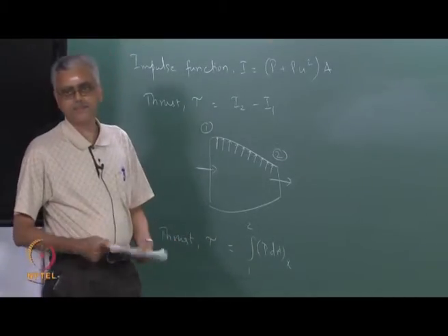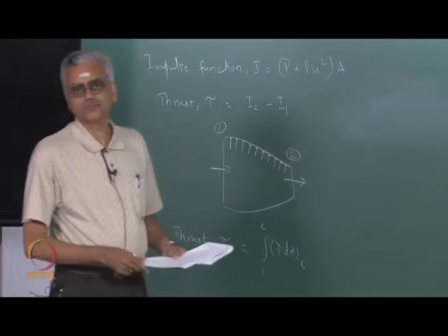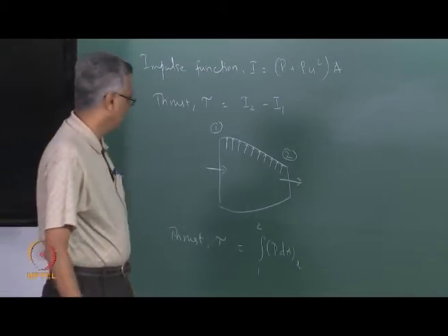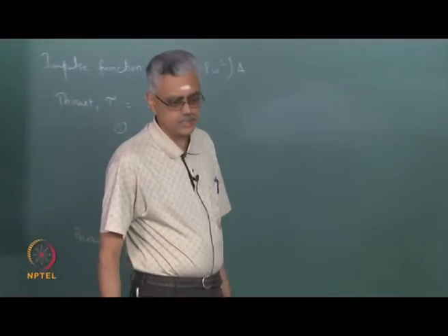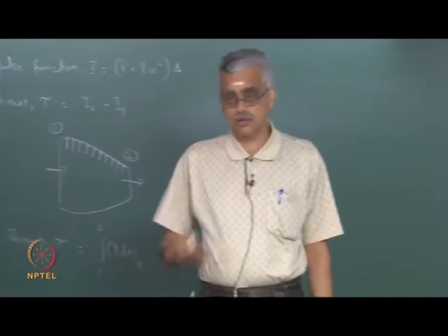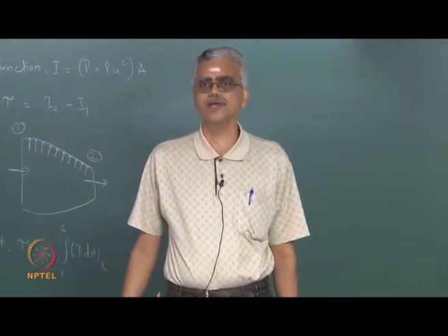Okay? Yes? So, if a solid rocket is having only a convergent nozzle, then it won't be able to produce thrust? It won't be able to produce thrust, correct. The solid rocket will not have a convergent nozzle alone, because the stagnation pressure in a rocket engine is very high.